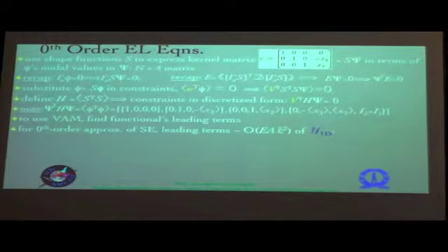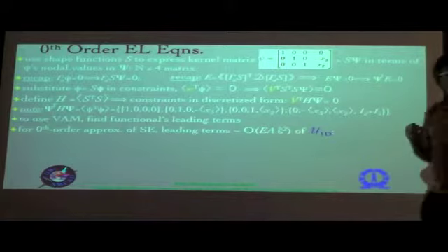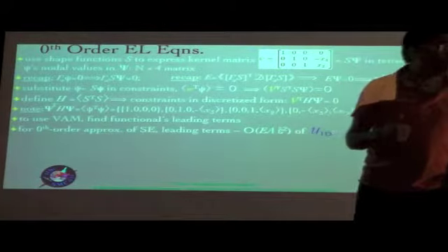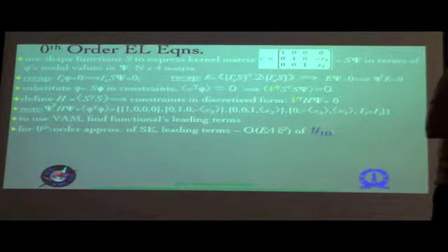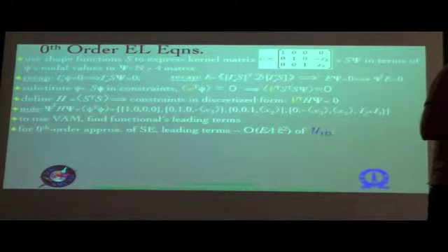So, what is not clear is why this warping W transpose multiplied with psi is excluded from that root G term. Yeah, what is excluded, the root G term? See, basically the root G, what is the source of that? The source of that is a volume integral, right? The constraints do not come from a volume integral, they come from a pure area integral. That means, particularly for this case, we can exclude the root G.